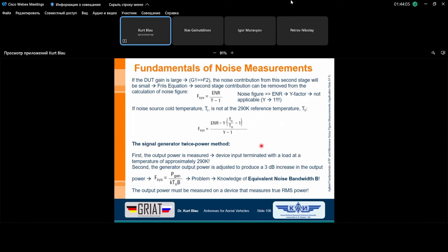It's normally selected by the rule that the noise figure should be as low as possible. And if we look at power amplifiers, means if we look at a transmitter as the last stage before the signal goes to the antenna, large radio stations, for instance, have power amplifiers which deliver not only 1 kilowatt, maybe 10 kilowatts or much more.